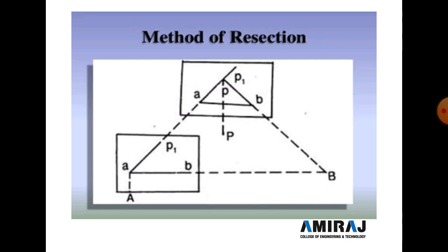Now the table is shifted and centered in such a way that P1 is just over the ground point P. The whole setup is transferred to point P, and the approximate point P1 on paper is just over the P point. For orientation, backsight the ranging rod at A, and with the alidade touching point b, bisect ranging rod B and draw the ray.